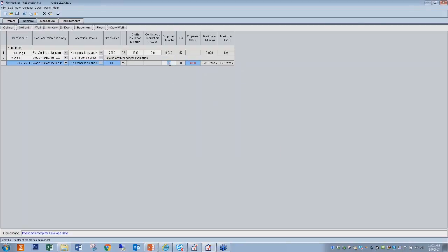All right, so I'm going to go put in a nice value that I know will work. Hopefully. All right, and then solar heat gain. What is this average thing over off to the right? Well, in the code, you can do area weighted average. But that area weighted average means that you're going to that prescriptive table, the U factor table, and the area weighted average is 0.35 for the U factor. I could have maybe 2 windows with a U factor that's higher than that, and it's the area, the square footage of that window, and then maybe ones that are lower than that.